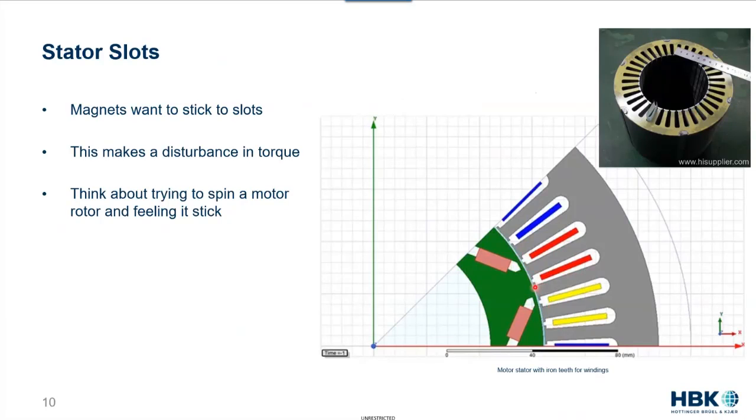So how torque ripple looks for a specific motor is strongly determined by the construction of the machine. How many slots there are, how many windings there are, what the magnet on the rotor looks like.